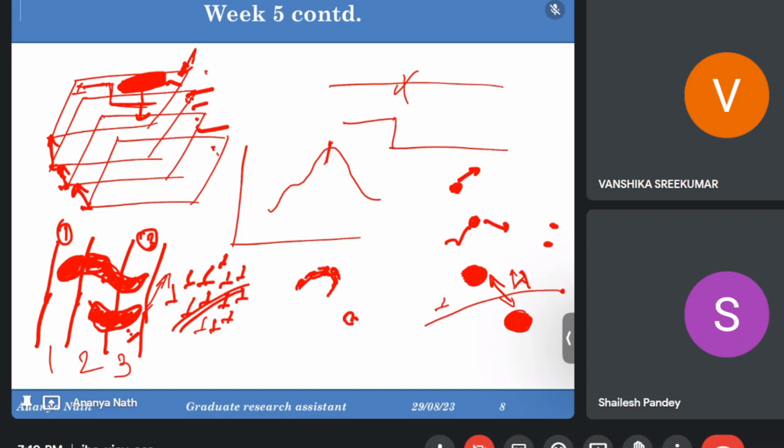So if the width is minimum, so stacking fault means there was previously one dislocation, but now because of the external load, the dislocation has been divided into two parts, and this position in between two dislocations is a favorable position for the solute atoms to sit. But a solute atom can sit only if the position is vacant and favorable for the solute atoms.